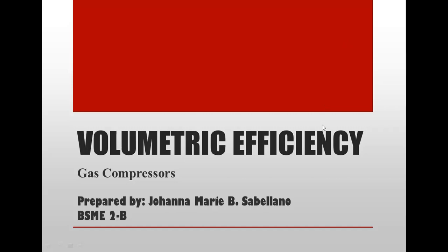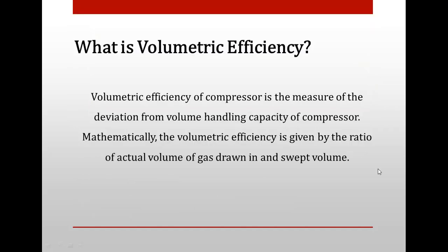Volumetric efficiency is the measure of the deviation from the volume handling capacity of a compressor. Mathematically, it is given by the ratio of the actual volume of gas drawn in to the swept volume. Ideally, the volume of air should be equal to the swept volume, but that is not the case in actual conditions. The volumetric efficiency lies between 60 to 90%,